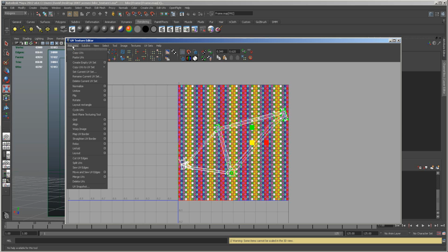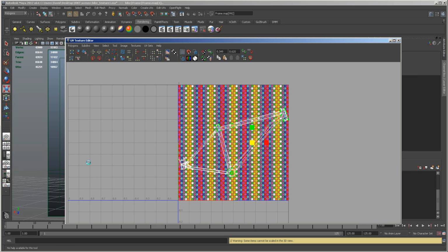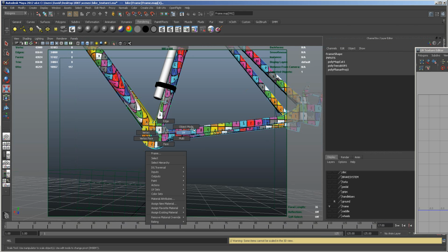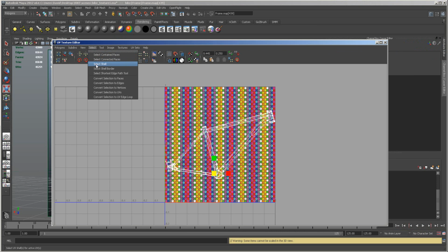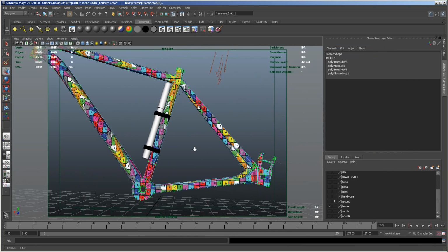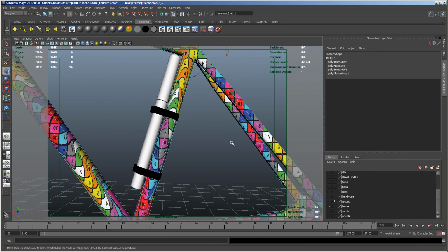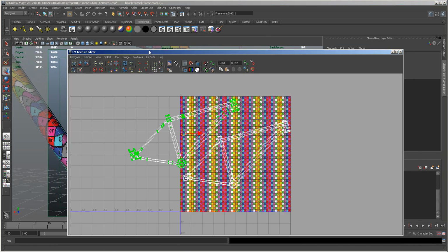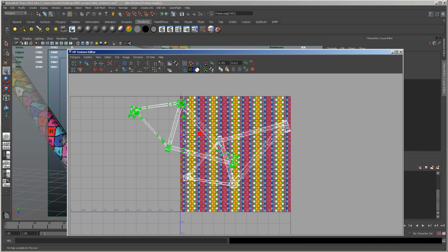Then I go to polygon and split the UVs, and now I'm hoping that if I click one of these UVs and come back in and select the shell, go to W, that it'll allow me to move it, which it does, which is great. So now I just need to check which side. Is this the wrong? Yeah, this is the right side. So I am on the right side for flipping. So in this case I'm going to flip it vertically like this. Yeah.